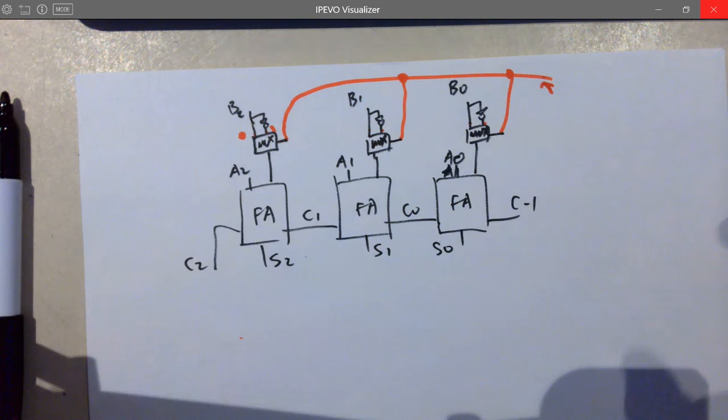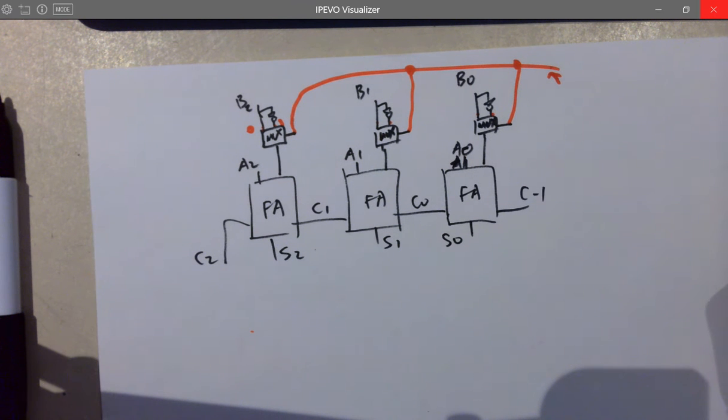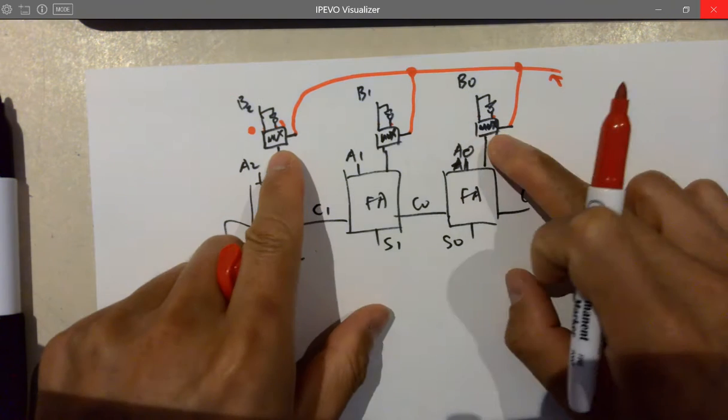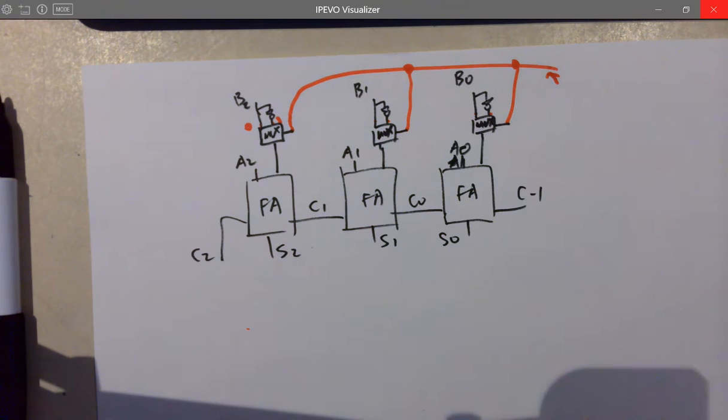So now the purpose is to make a subtractor. It's 2's complement. Whenever this is adding a negative number, it's actually making a subtraction. So in that case, you need to invert that data and plus 1 to make a 2's complement, to get the negative number of it, right? That's the purpose. And now we are using a mux to implement that function.